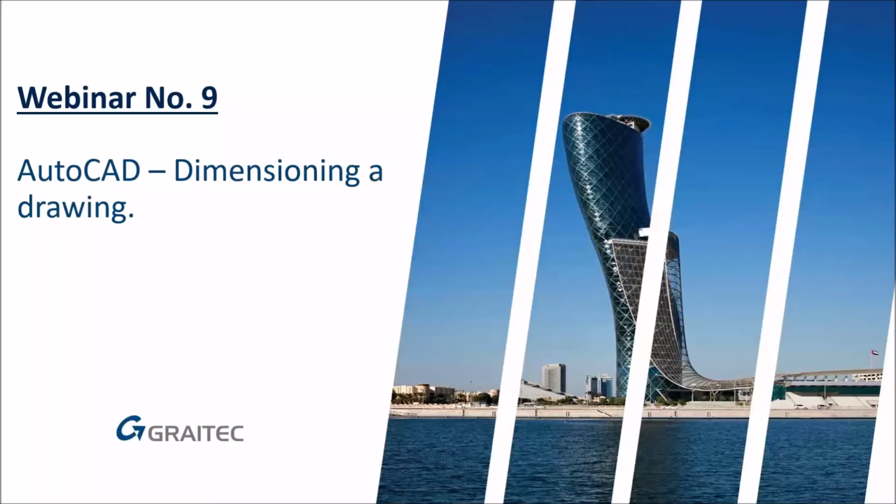So I'll have a look at creating some dimension styles, and also transferring a style from drawing to drawing. Because it's okay to set up a dimension style in one drawing, but then you open another drawing, and it might not have your dimension style in it. Now, if you're working with drawing templates, starting new drawings, brilliant. But what if you receive somebody else's drawing from down the road? Joe Bloggs Architect on the road sends your drawing file down. It won't have your dimension style in, will it? So in that case, you need to transfer the style from drawing to drawing. It's dead easy, dead quick. You don't go through rejigging the dimension style from scratch again.